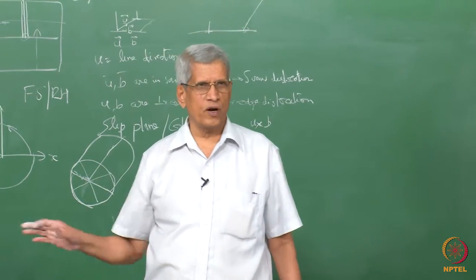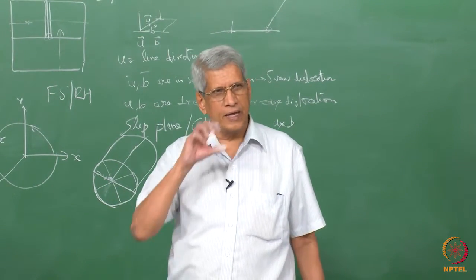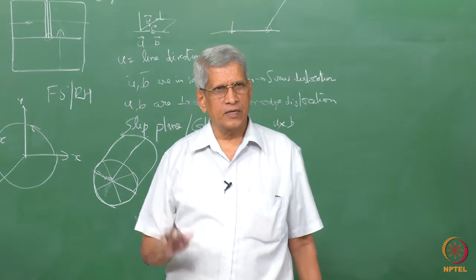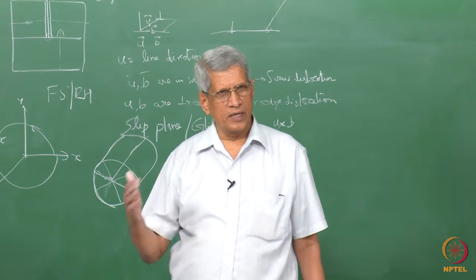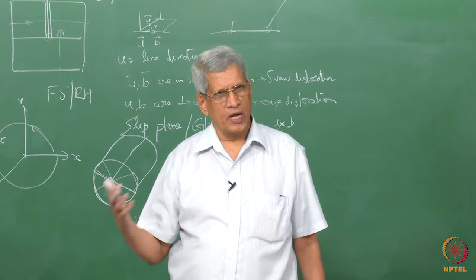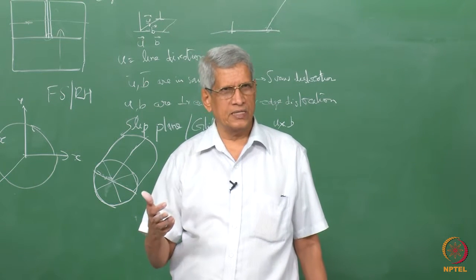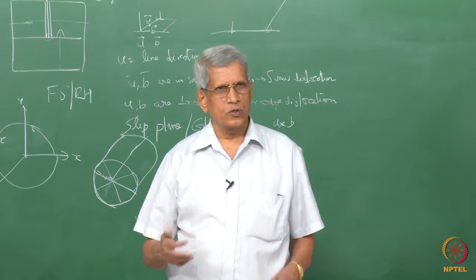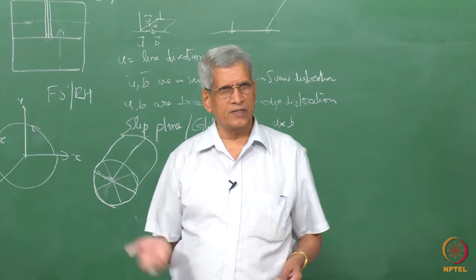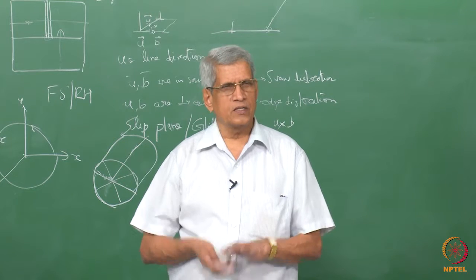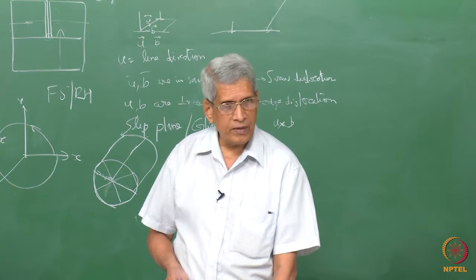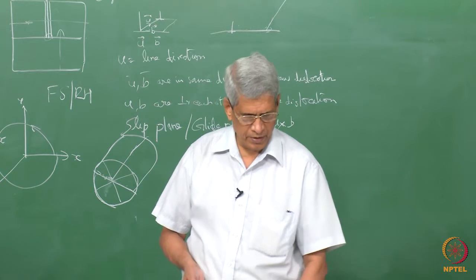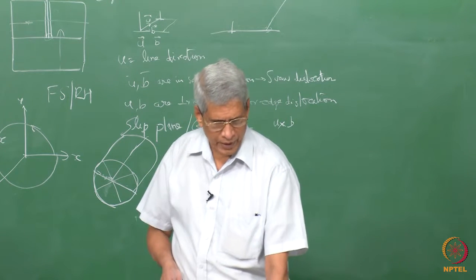But at this stage, what one has to understand is that for an edge dislocation the slip plane is defined, given by the cross product, and by the same cross product for a screw dislocation the slip plane is not defined. So any plane which contains the line direction is a potential slip plane for the dislocation. Okay, that is clear.